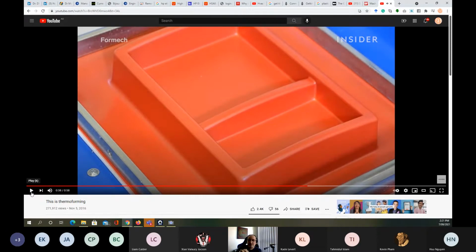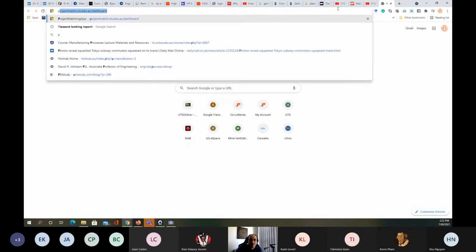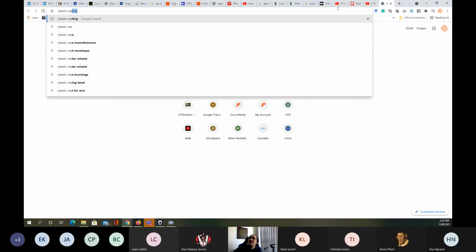Okay, I got that. That's what we call the thermoforming process. So I can make the valve by thermoforming, by casting, plastic casting process, making the mold with this method. That's one mold. I can repeat the process 10 times and have 10 molds. Then I start to pour the resin in it and make what's called the plastic casting.